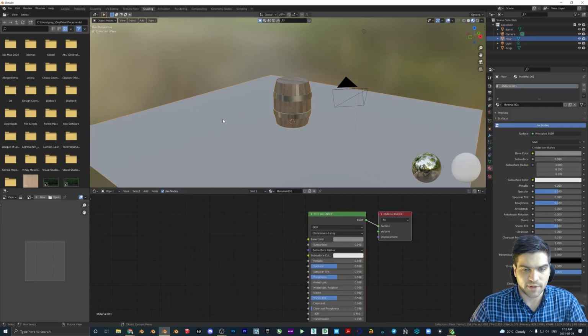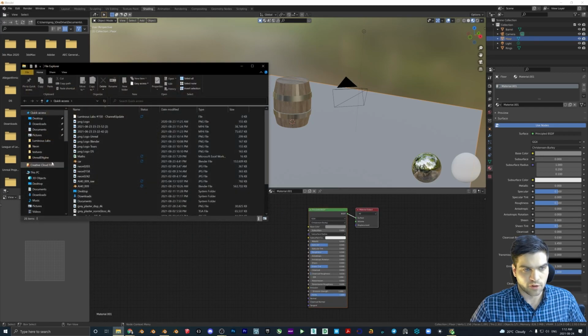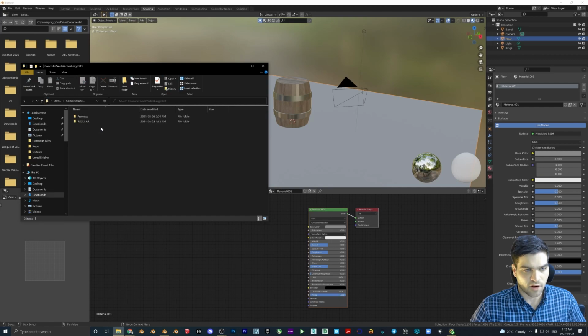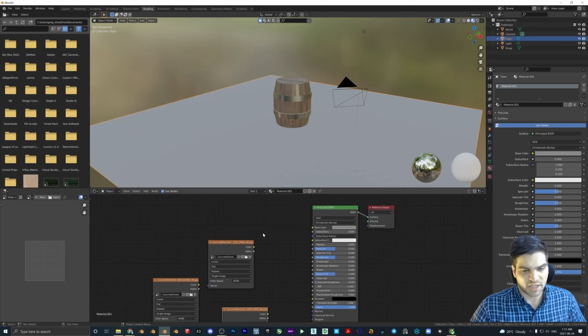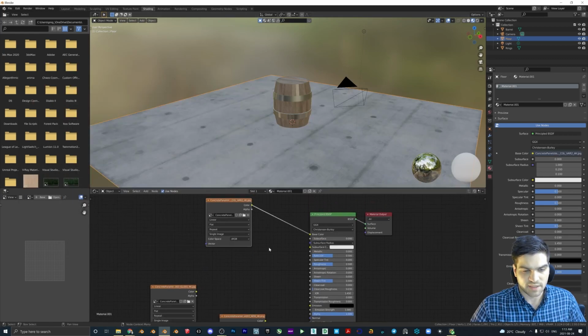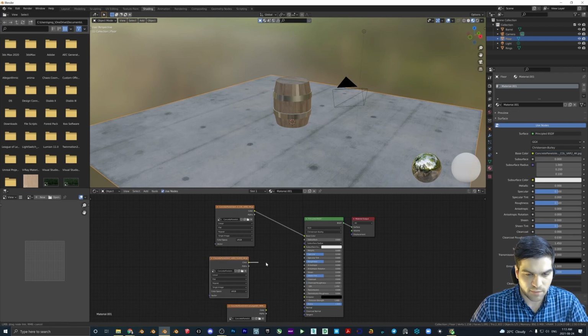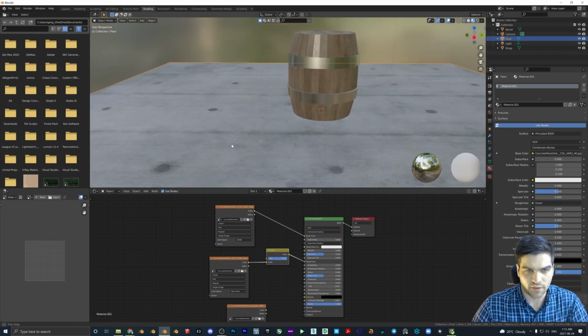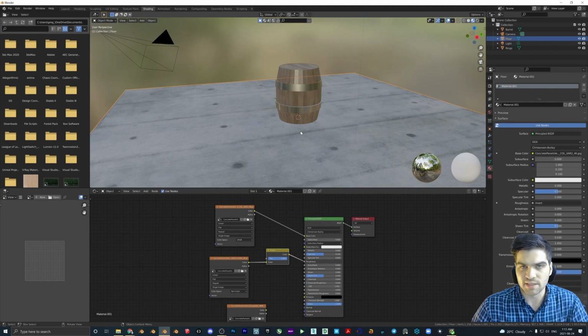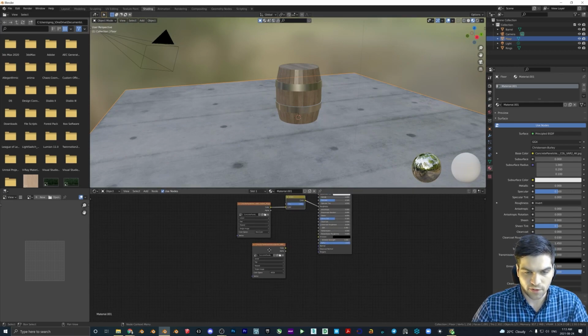So let's pop in here. Let's open up our File Explorer, Downloads, find the concrete panels, vertical large, 4K, and let's choose variation 2, gloss, and normal. That should be fine for now. Let's plug this in here. Now, the gloss map can plug into the roughness map, but we do need to make this non-color. We also need to Shift A, search invert, drop that in. Now it is a roughness map. That's literally all a gloss map is. It's an inverted roughness map, so they're interchangeable.